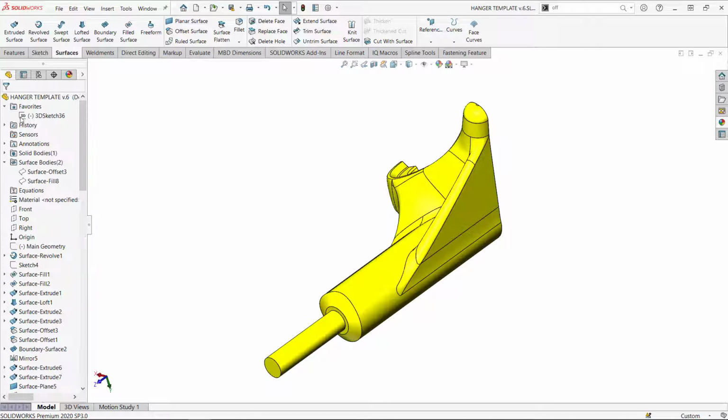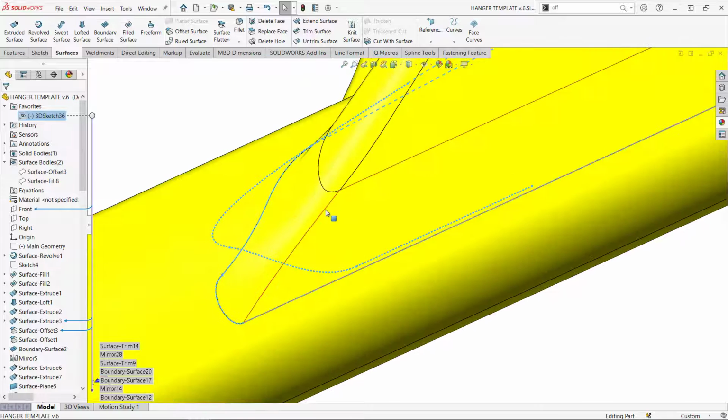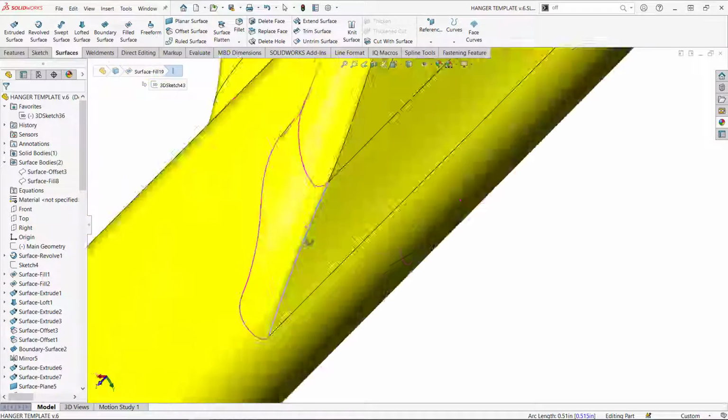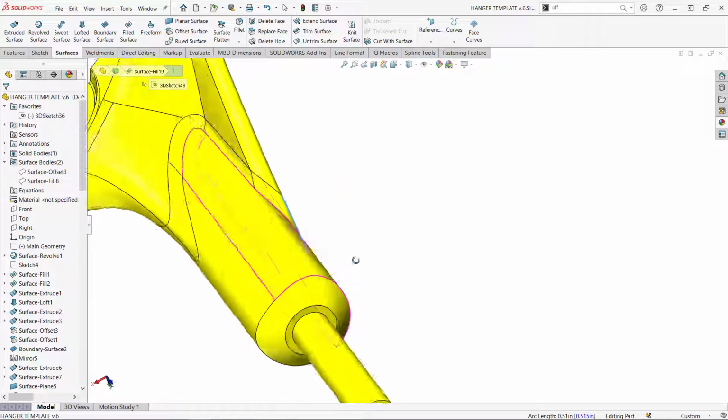At this point, if you want to do further improvements to the blend, you have quite a few things that you can change. One is this 3D sketch. Maybe think about ways to change this area. The other one might be changing this specific edge. Do I want to come up to here somewhere? Will that give me more freedom when I'm going around this? Or think more about divide and conquer, doing smaller faces in this area.